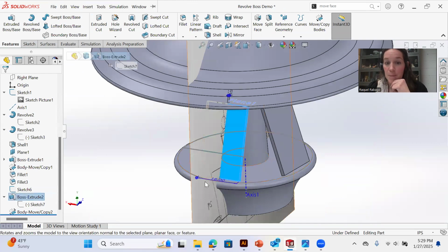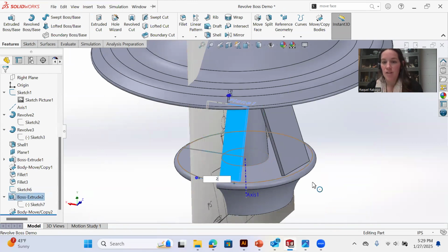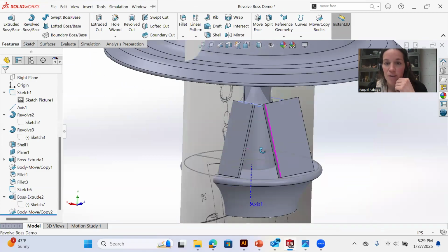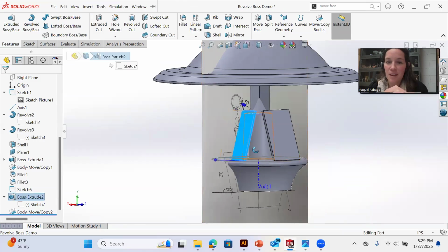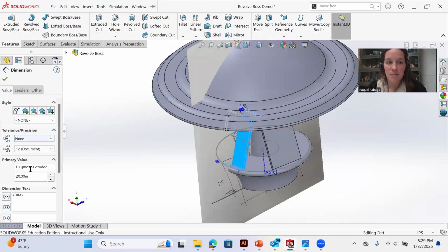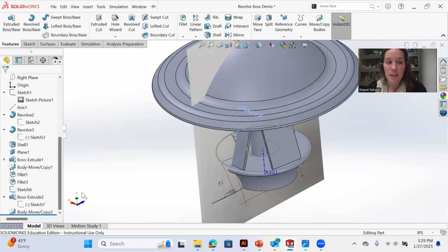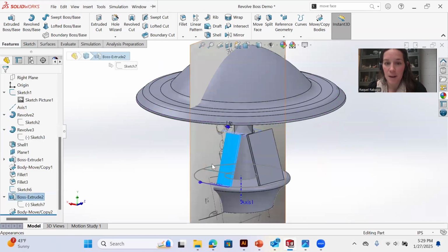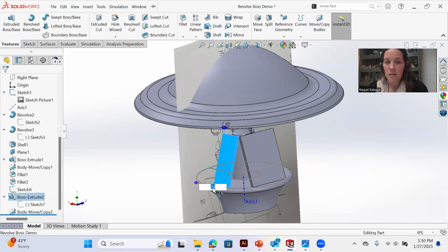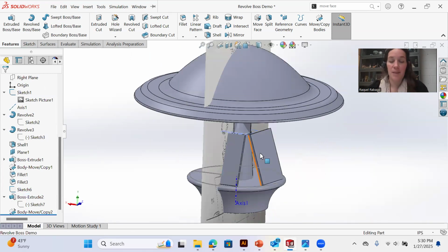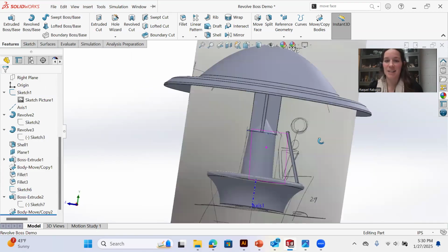So maybe we'll go a little bit bigger, about 20 inches. Now we're getting into the, we're just tabbing things just slightly. Might be fun to do, might be annoying to do. But it does update both of those since we're copying that body. There we go. So if you see something and you've changed it and it's not reflected in CAD, in SolidWorks, you can hit Control and B. So let's see, 22. Okay, it rebuilt it that time. Fine. It's gonna make a liar out of me.